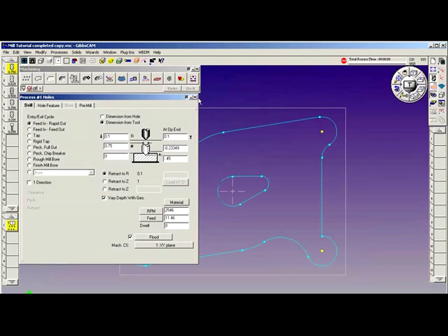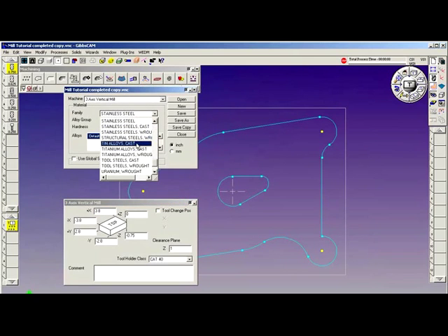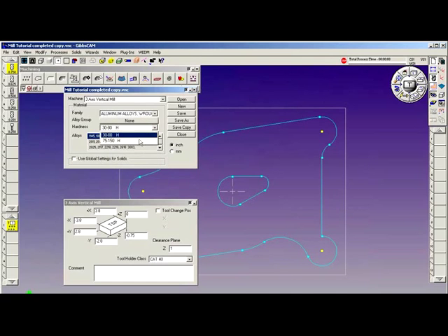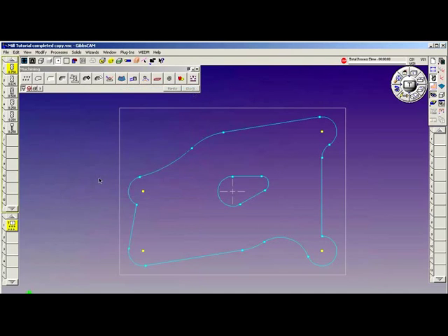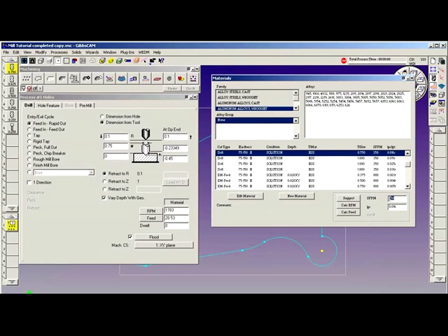If I come back over here, change my material to aluminum alloys, in the wrought condition, I'm going for 6061, change the hardness from 75 to 150, and in my alloy window, I should see 6061 as part of my selection set, and I do. So I've chosen correctly, close the dialog, double click the process again. Notice that right off the bat, the RPMs have increased as well as the feed. If I go back to my material dialog, these are the recommended values.